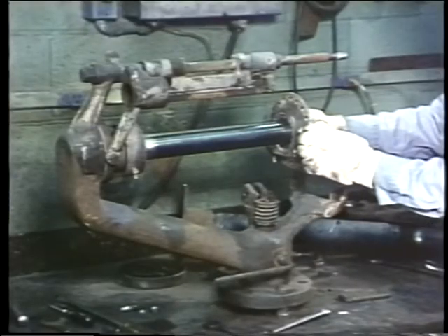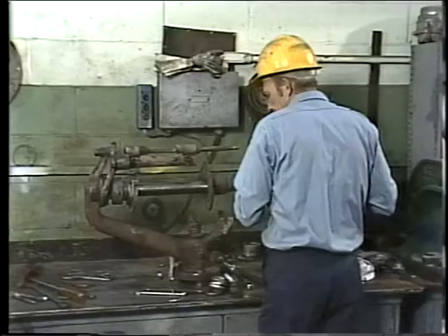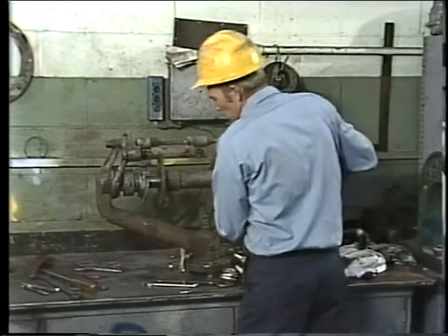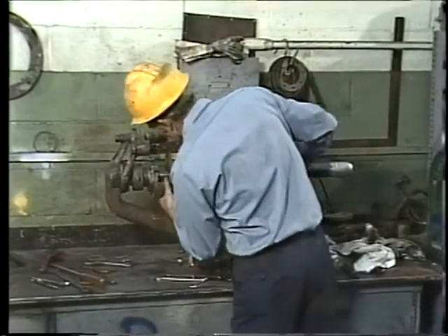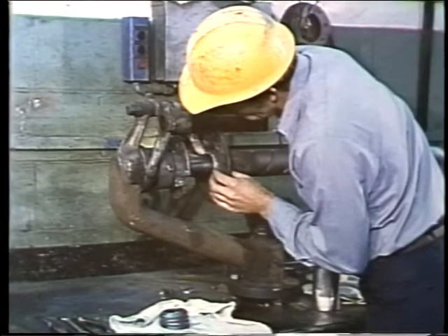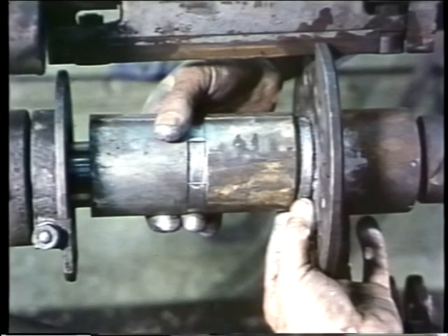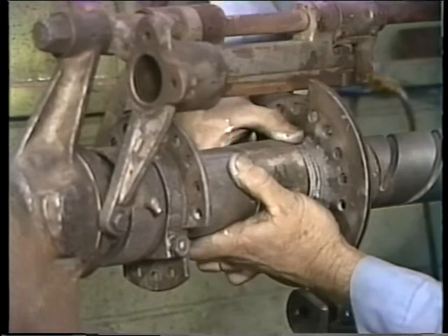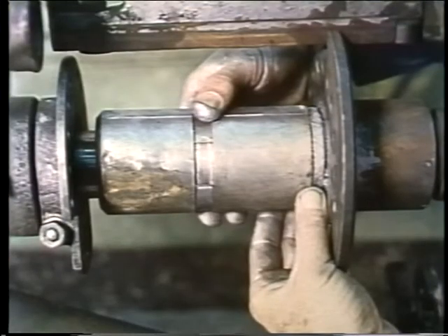Now we're ready for the gland follower and the element to go on. The element just slides on over the feed tube pretty easily since the packing's not in place yet. Tube packing is done after the element is in place over the feed tube. Just like with the valve's packing, the gaps of each ring are staggered. The split section of pipe he's using makes it easier to stuff the packing in uniformly. The beveled end is used on each of the tapered packing rings. For the last ring, which has a flat outer surface, the squared off end is used.